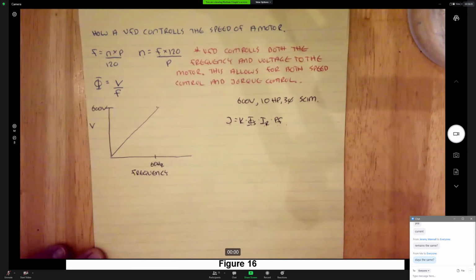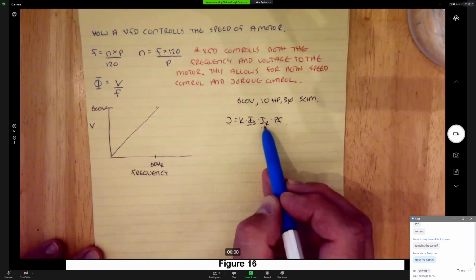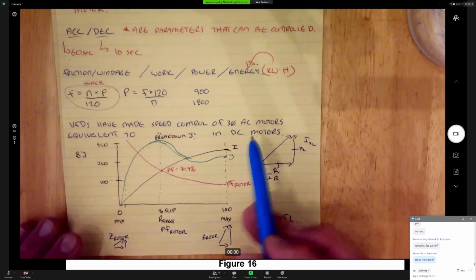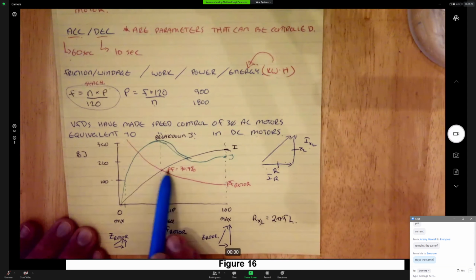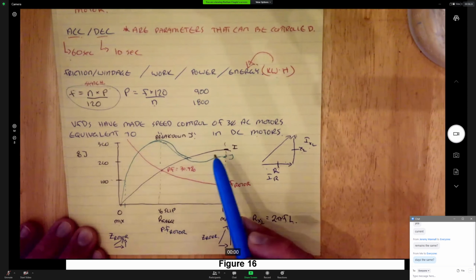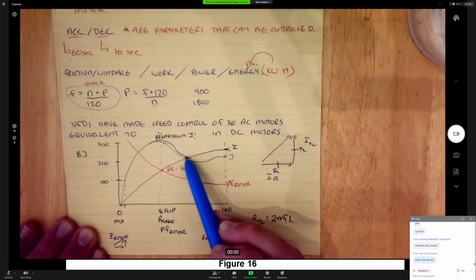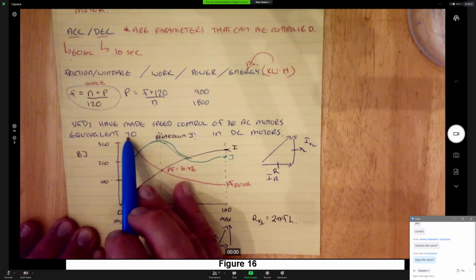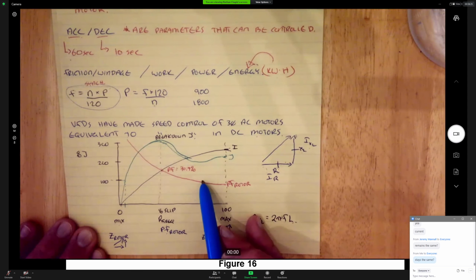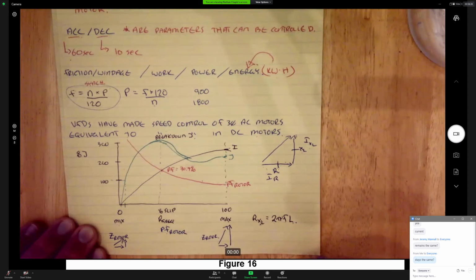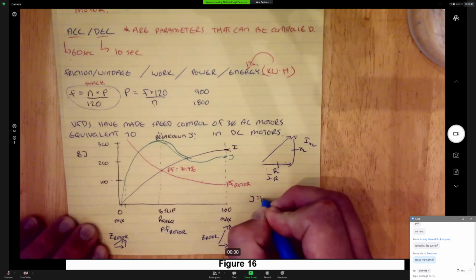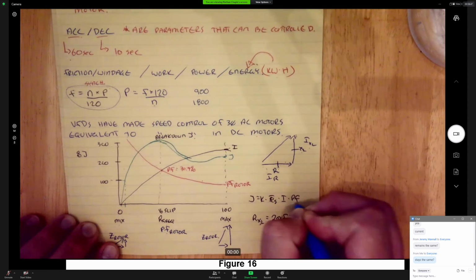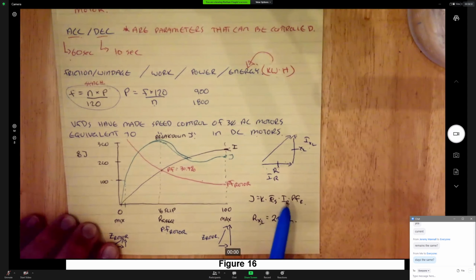So let's look back one more time, and I want you to look at the power factor and the rotor current with me for a second. Do you see how the rotor power factor starts off low and increases to a maximum? And then the current starts at a maximum and then decreases to a minimum? And they kind of have similar shapes to their curves here. So what I would suggest is with that formula, and I'll write it here as well, just so we can make sure we're all getting it here. Okay, it's all in the rotor.